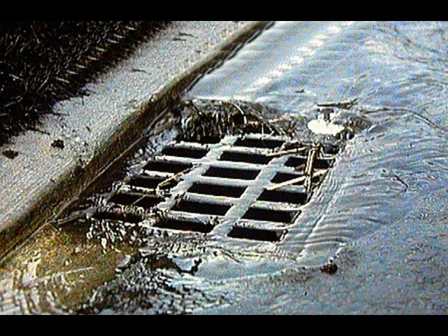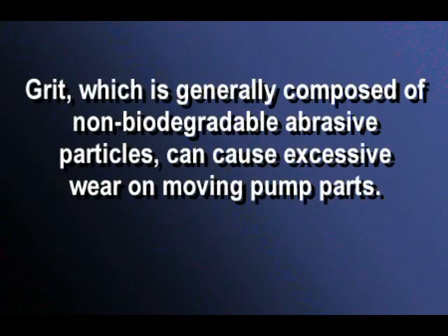Incoming wastewater can also contain large amounts of sand and grit, especially if the influent includes stormwater from a combined sewer. This grit is abrasive and will damage pumps unless they are specially designed. For example, pumps used at the influent end of the plant would have impeller designs that are made specifically for grit-laden liquids and would be constructed from abrasion-resistant material.